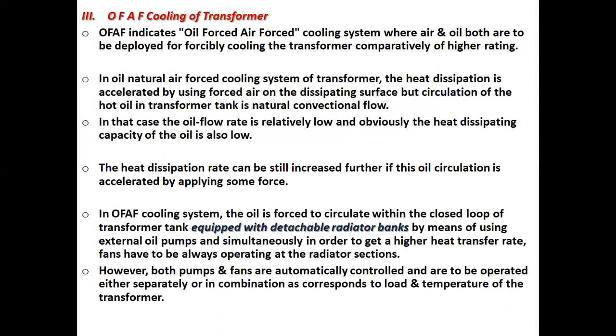In that case, the oil flow rate is relatively low, and obviously the heat dissipating capacity of the oil is also low. The heat dissipation rate can be increased further if this oil circulation is accelerated by applying some force. In the oil forced air forced cooling system, the oil is forced to circulate within the closed loop of the transformer tank equipped with detachable radiator banks by using external oil pumps, and simultaneously, in order to get a higher heat transfer rate, fans have to be always operating at the radiator sections.